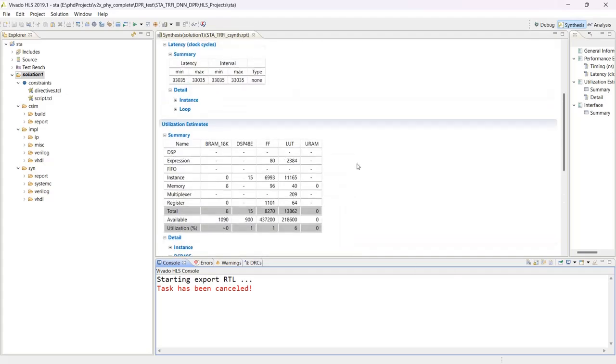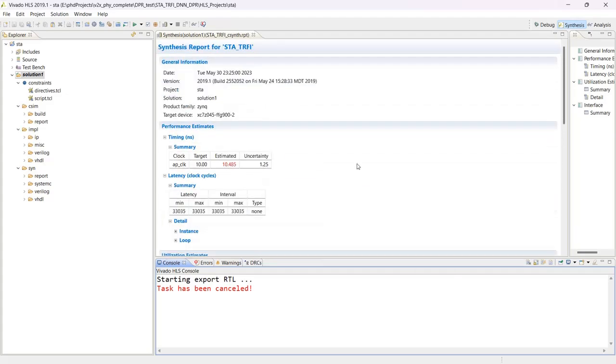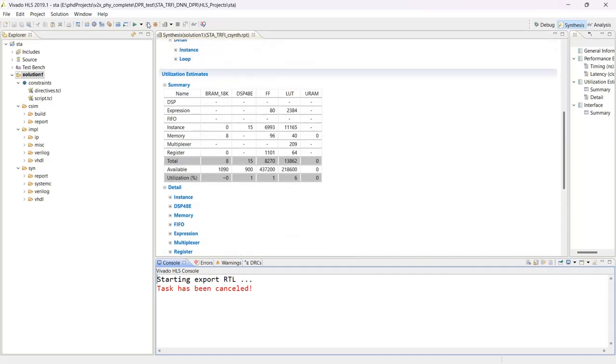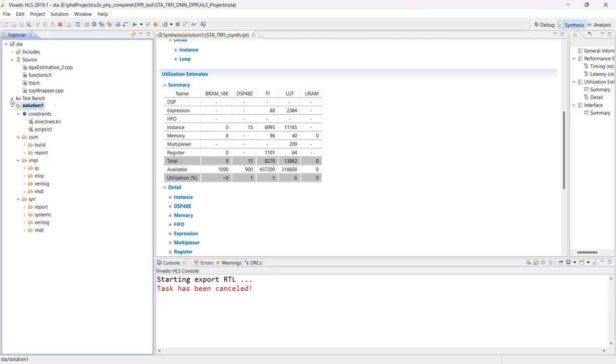Now, as I said, this is the normal Vivado HLS flow where we generate the IPs using Vivado HLS. So we will proceed normally with this. We will first have all the source files here, and then after simulating and verifying the functionality, we will go for synthesis, co-simulation, and finally, this is where we need a slightly different approach.